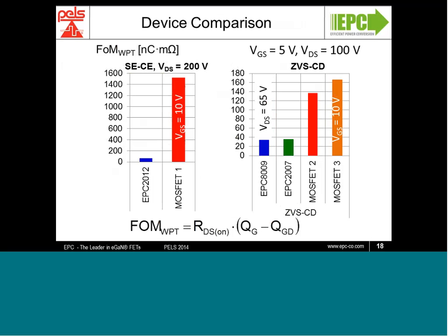To my knowledge, there is no MOSFET available at this voltage that can operate with a logic gate. So there's one disadvantage already that the GaN FET has over the MOSFET. And secondly, the voltage must be chosen higher than expected for power level, because it might turn out when you do your optimal analysis and design for your circuit, you say, oh, 100 volt MOSFET or device is sufficient.